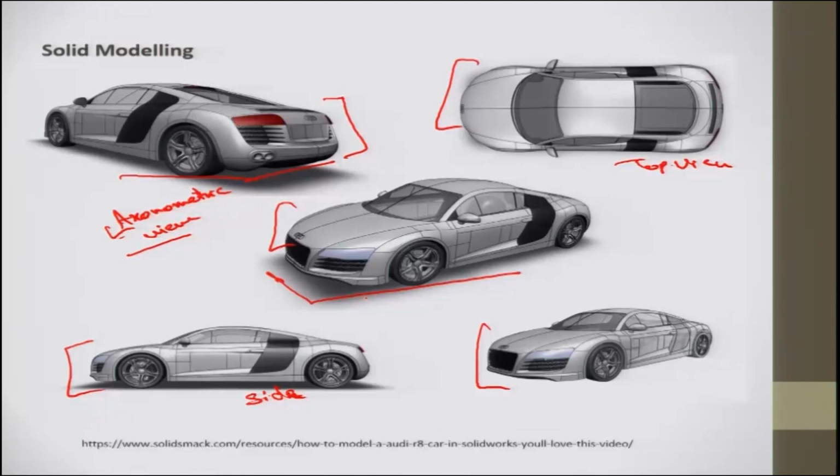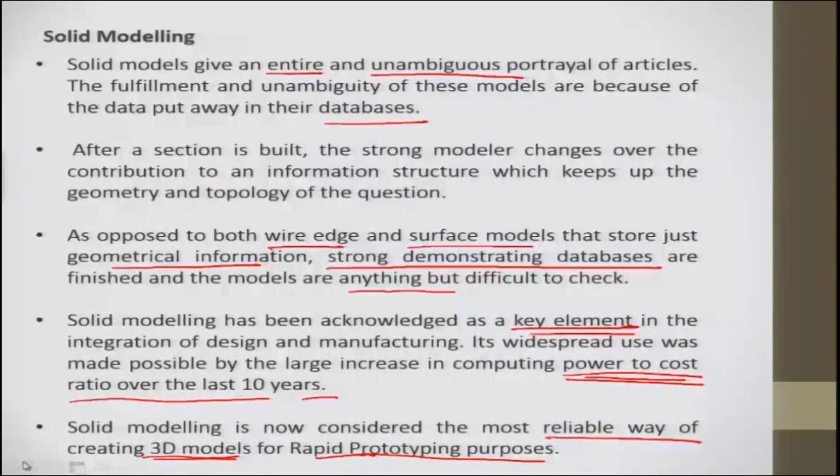The machines which are used to manufacture these 3D models manipulate the data before manufacturing so that they can use it. So 3D models, even in traditional manufacturing, are converted to G codes. In traditional manufacturing, it is G and M codes, that is in CNC manufacturing. In rapid prototyping, it is data manipulation.